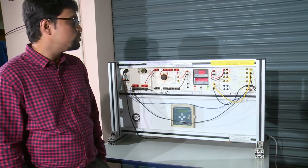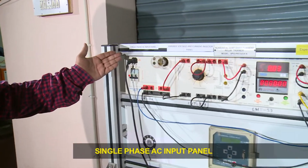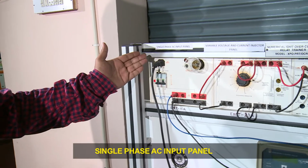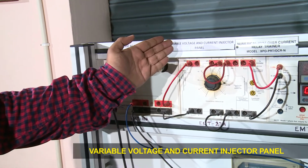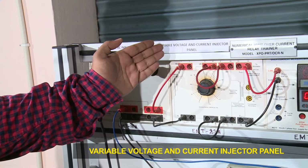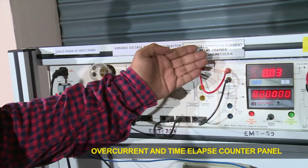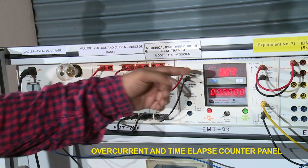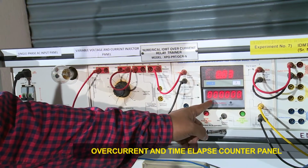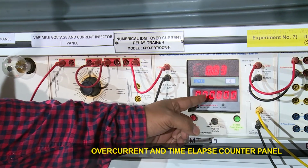Now there are 5 units of this IDMT overcurrent relay trainer. First we have a single phase AC input panel to supply the input power. Next we have a variable voltage and current injector panel to vary the input current. Next we have an overcurrent and time elapse counter panel to see the values of the current and to see after how much time the relay is tripping.